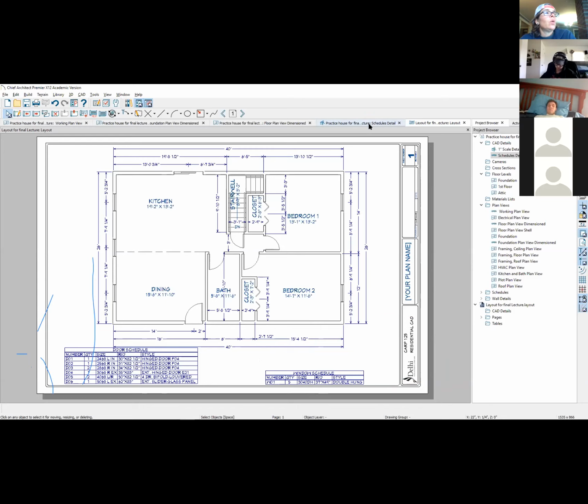The other thing that I wanted to do, notice that our door schedule gives our windows and our doors a number, but we are missing the corresponding callouts in our plan. And this is because the layer set that we are using for our floor plan does not have the window and door labels turned on.